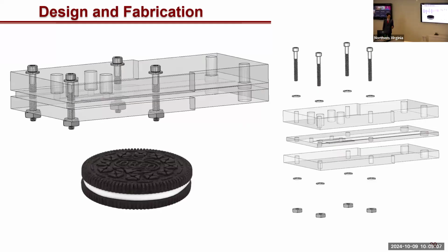This is what I was talking about in the future work. That bottom plate, that's what the microchannels are pressing up against. That's made out of acrylic. Acrylic doesn't have very good adhesion to PDMS, so you could use glass for that. And glass has very good covalent bonds with PDMS. Thank you.